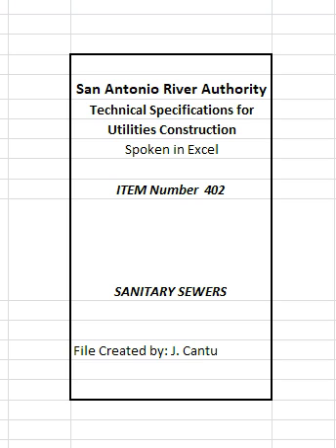No pipe shall be installed in tunnels except as provided on the plans, or with the permission of the engineer. If the contractor finds it necessary to install pipe in tunnels not provided on the plans, he shall submit to the engineer, prior to commencement of work, a detailed outline of procedures, methods, and use of materials depending on existing soil conditions. No horizontal or vertical curves shall be permitted, except as authorized by the engineer.